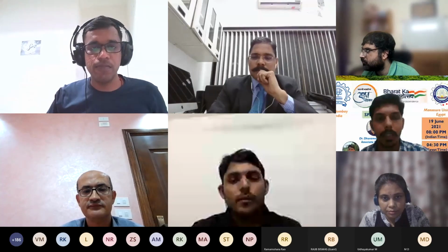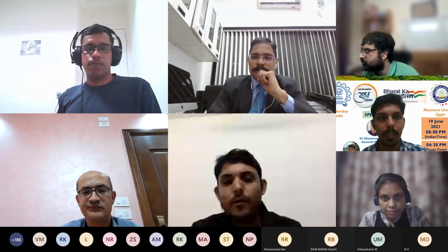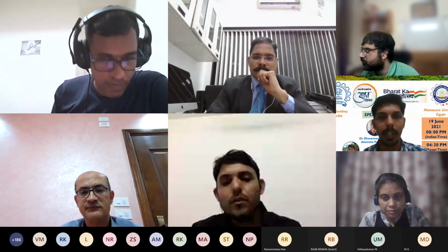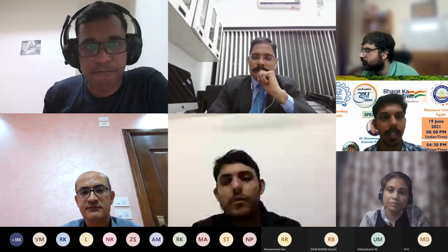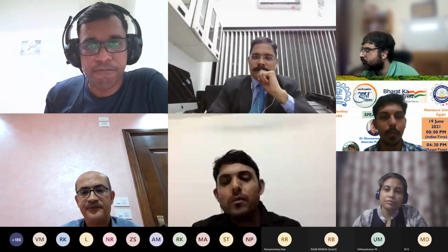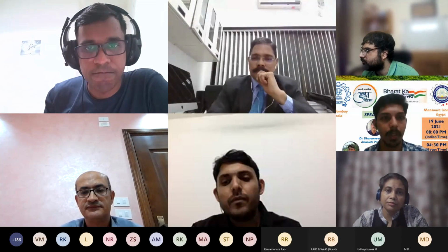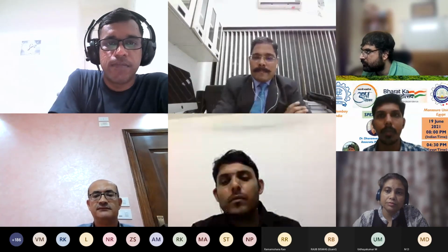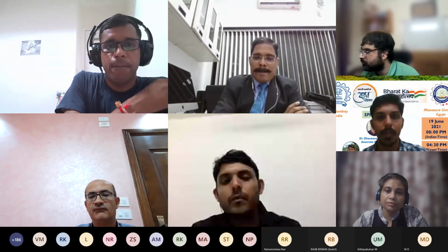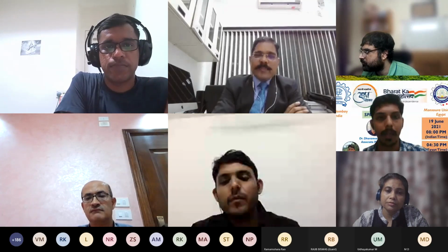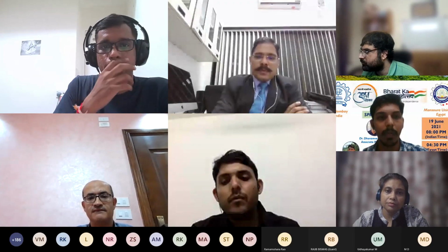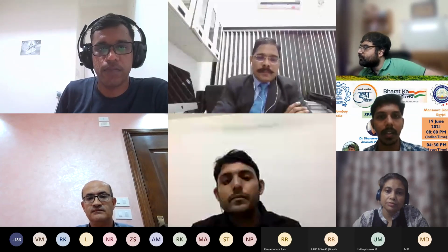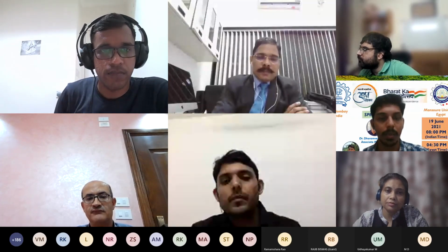Yes. It is all about the type of mix we are going to use, based on the traffic and climate conditions. I think selecting aggregate size means the nominal aggregate size, I hope. It is all about the type of layer we are using and where we are using it, the traffic levels and climatic conditions, and what type of performance we are expecting. Based on that, we need to select whether a fine gradation or one towards a coarse gradation. So I think that's it.